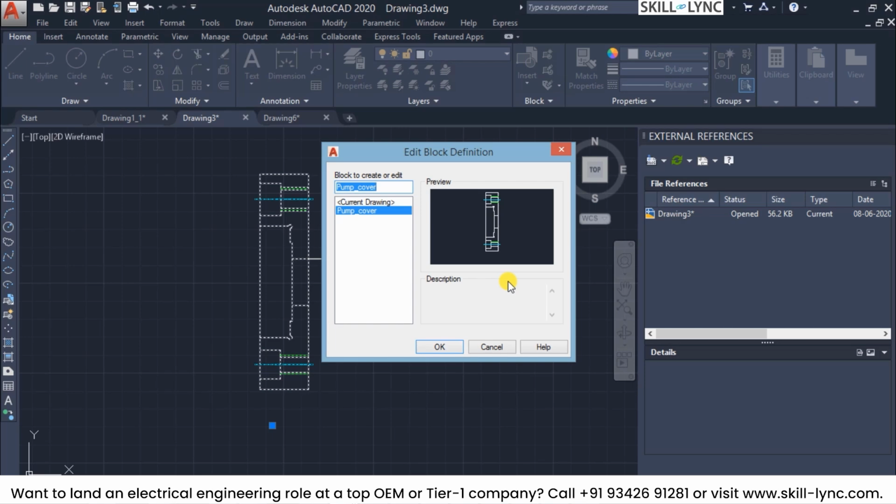This binding is going to be useful in two cases. One is that once you have frozen all the designs of the subcomponents and you're proceeding with the final assembly drawing, and then you just have to store it away or archive it in a location, then you can use that. You can take away all the references of the individual drawings and make it a single drawing. Or the other case is if you're integrating all the components of all the designers together and then proceeding to the next stage, and from here on you do not want to differentiate between the different parts and you want to retain all those as a single component in the current drawing, then you can use the external reference as a bound reference. So this is about the external reference binding.